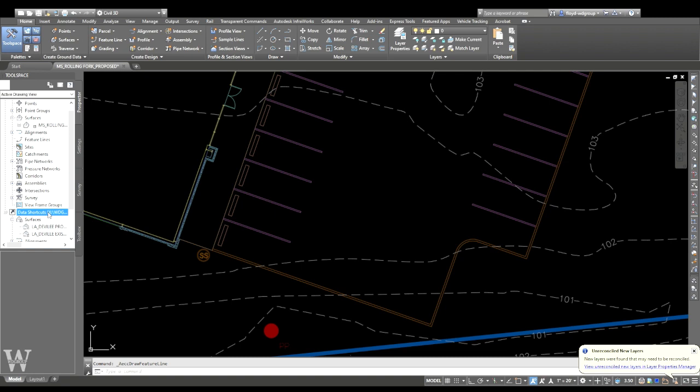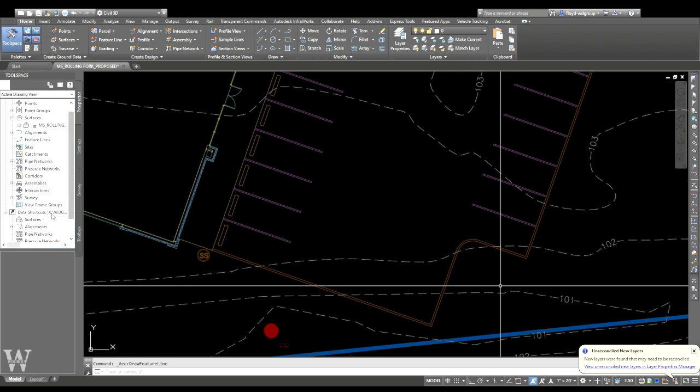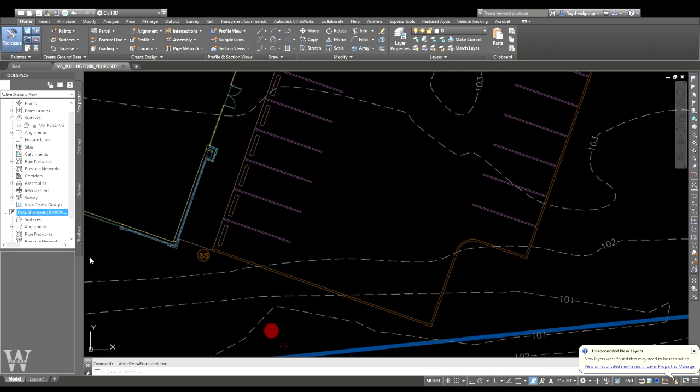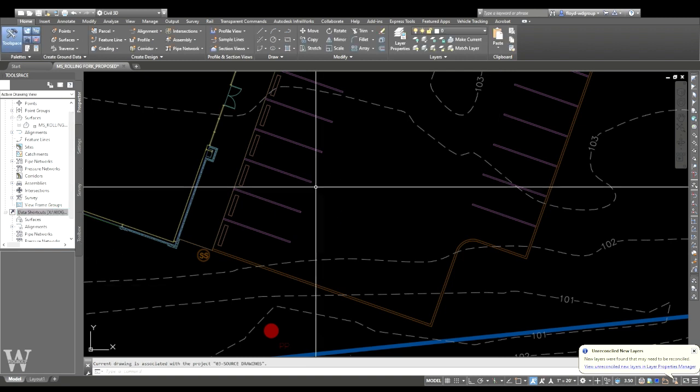And data shortcuts are nothing more than the way Civil 3D objects relate, like XReferences. So I can XRef or shortcut in something to a project later. You can do some research on that. So I'm going to set the working folder for this, and it's going in my folder here, and then I'm going to immediately associate a project to the current drawing, and it's there.